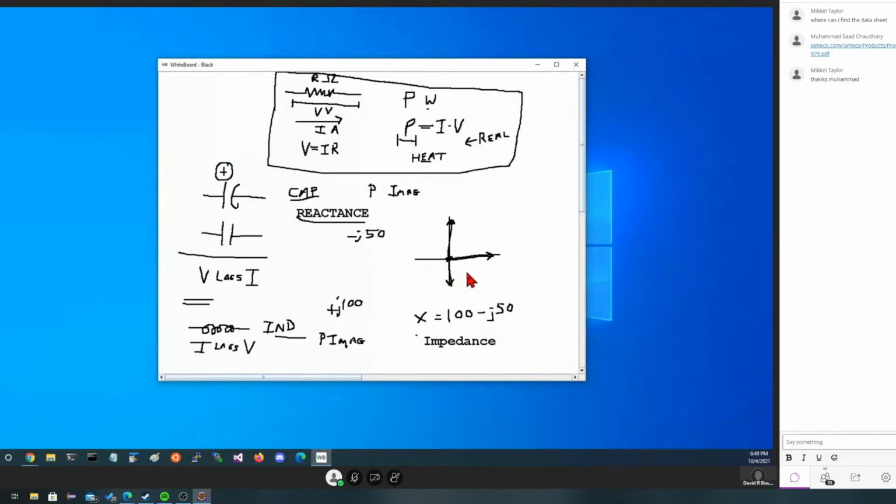Now, if we have a circuit which has some inductance and resistance, which we can measure, we're going to look at what value the actual impedance of that particular circuit is. We also might have capacitance in our circuit. If we have capacitance in the circuit, and in this case, this one's a little longer than that one, we're going to wind up with a vector which says we have more positive than negative impedance. So we'd have a plus J on it. We're still working with reactance there because it's only the right-hand half of the complex number.